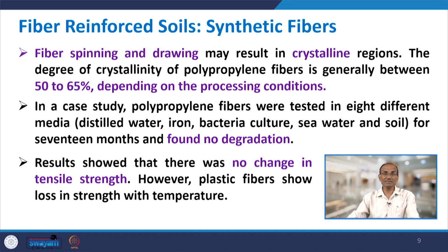That means they are resistant to degradation even if the media in which the fibers are placed are different types, not necessarily distilled water. It could be bacterial water, culture, or seawater, which is normally brackish or salty water. Further results showed that there was no change in the tensile strength, however plastic fibers show loss in strength with temperature. So, as far as polypropylene is concerned, they are good, but plastic fibers may decrease their strength.